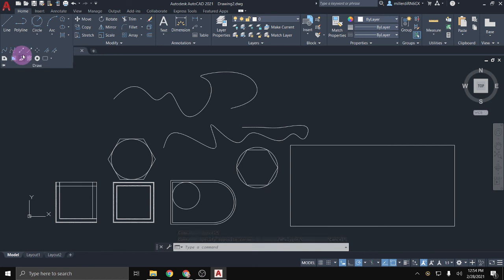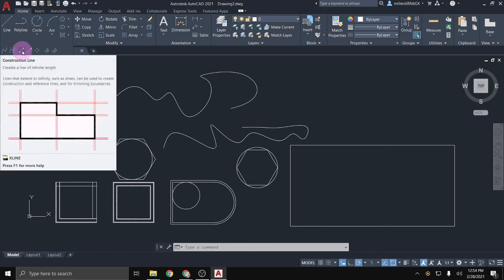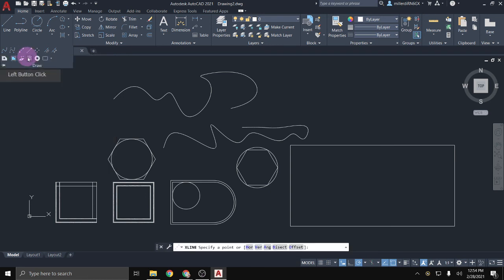Another tool that I'll use kind of often for architectural drawings is a construction line, which is keyboard shortcut XL. And it just will help me kind of align my different views. So when I'm looking at my floor plan and I just want to project guidelines down for my elevation, I can use the construction line tool for that.